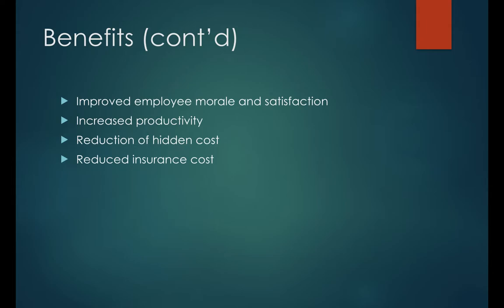So we all know, well, we haven't discussed in this class, but there is an EMR, the experience modification rate that's established for your insurance provider. The way your insurance does your rating is they look at how many injuries you had on your previous projects, and that's the rate they're going to give you on your current projects. On most projects, you have to meet a certain value. I believe it's one. You have to be at one to be average. I'm not too sure if you're above or below.